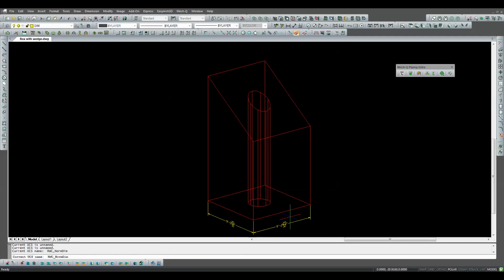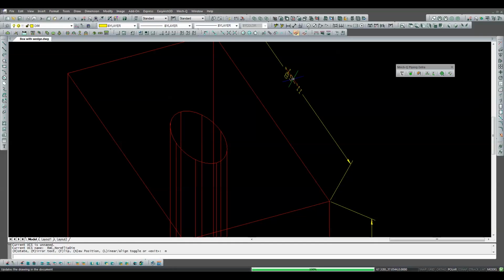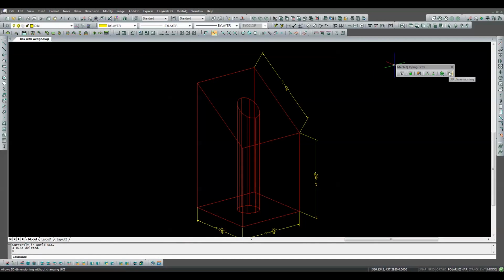When you dimension in 3D space, there's no need to change the dimension to an oblique angle, no more need to set the oblique angle for your annotation text, and no more erasing dimension lines because they aren't what you expected. If the dimension text appears mirrored or upside down, simply type the letter M for mirror or F for flip on the command line to manipulate the text to the correct orientation. There's no limit to how many times or in what combinations the text line and the text can be manipulated. You decide when you're satisfied with the dimension appearance.